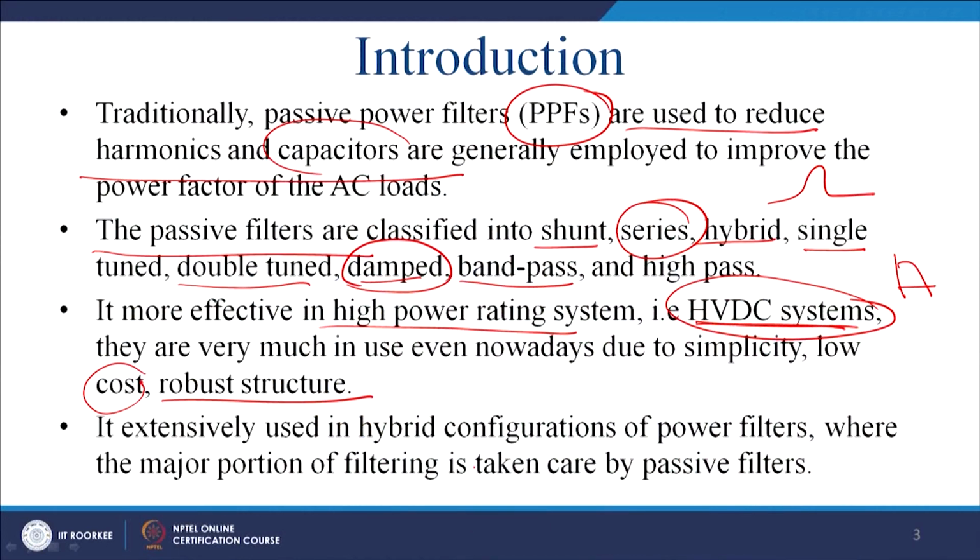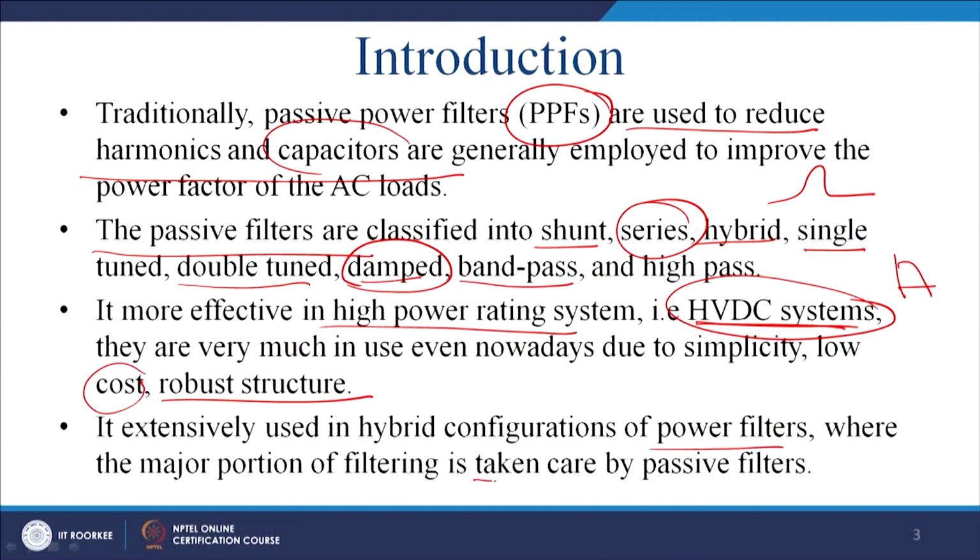The extensive use is in hybrid configuration, that is, the configurations of the AC and DC both, I have seen. I will show some examples of the hybrid filter in the topological discussion of the shunt active power filter. So, configurations of the active power filter, where the major portion of the filtering is taken care of by the passive filter,